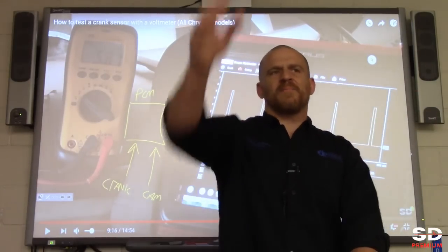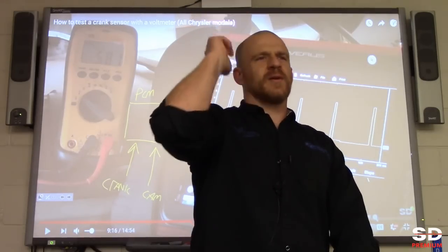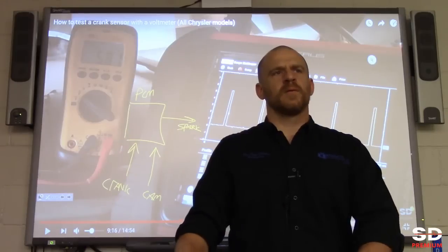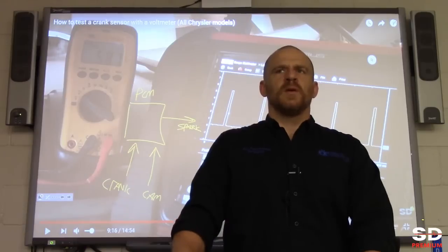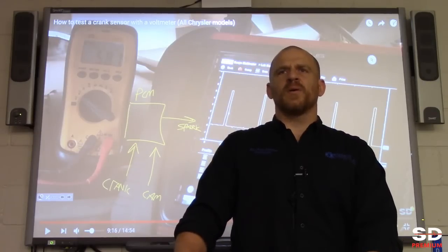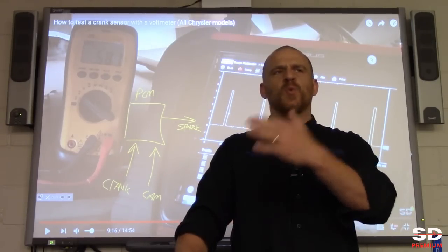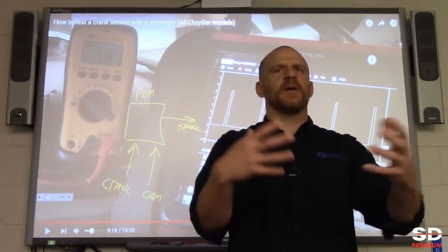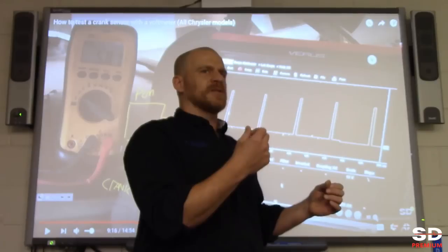I don't mean to disregard what you said. You want to say that again? It could possibly be like a protective device, so that if the engine is out of time, it doesn't bend rods and destroy itself. I'm sure some of that logic's in there, but that's primarily not why we would need both signals. What this would have to do with is coordination of the timing, as in our valve timing and our spark timing. And on this design, I believe this was a waste spark system, but I'm not 100%.